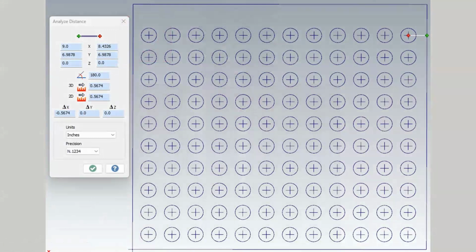Before starting the machining process, the selected tools need to know where to go on the block. We used a software called Mastercam to create a 2D model of our block as shown. This toolpath was our final design to utilize as much space as possible on the block to thoroughly test tool wear while abiding by the quarter-inch wall thickness minimum provided by Quaker Houghton.